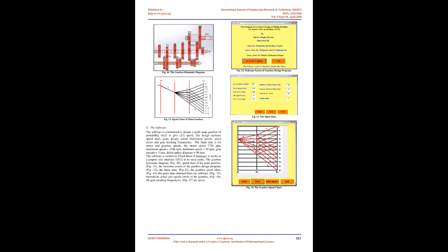Both excitation and structure natural frequencies must have different values for avoiding the risky response effects. Sources of forced vibration in machine tools are generated mainly from the rotating elements of the machine itself or transmitted from near vibrating machines. Electric motor, belts, pulley, shafts, bearings, gears, spindles are probably sources of forced vibrations.